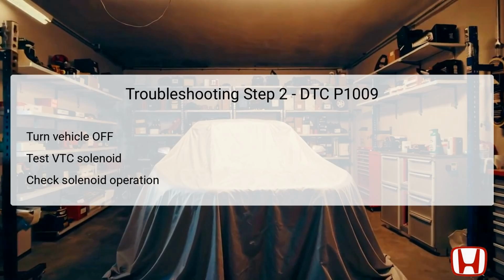The second troubleshooting step involves verifying the operation of the VTC oil control solenoid valve A. Begin this step by turning off the vehicle to ensure safety during testing. With the ignition off, proceed to test the VTC oil control solenoid valve A for functionality. The solenoid should respond appropriately when voltage is applied, indicating it is operational.